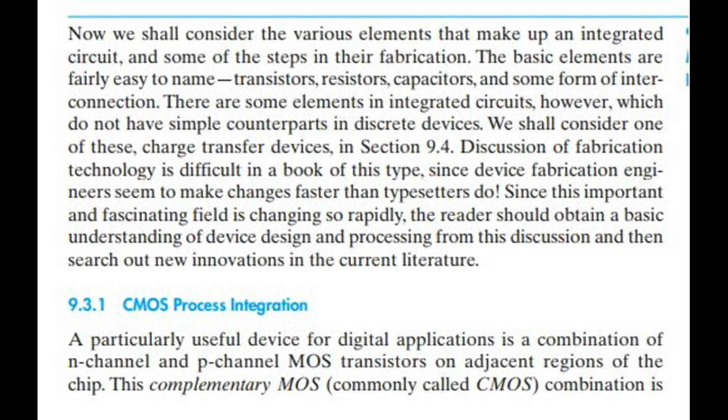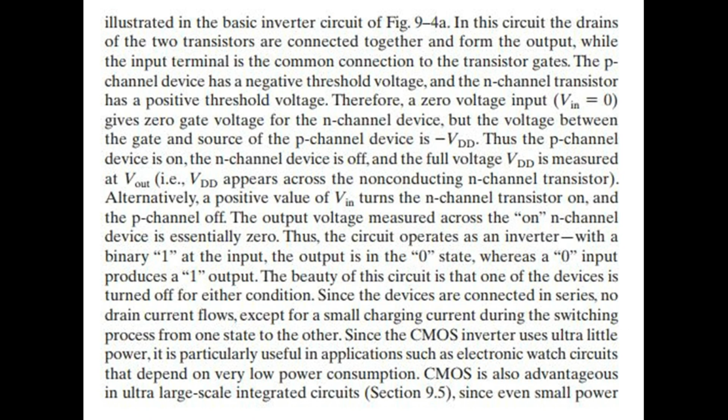Complementary metal oxide semiconductor process integration. A particularly useful device for digital applications is a combination of N-channel and P-channel metal oxide semiconductor transistors on adjacent regions of the chip. This complementary metal oxide semiconductor, commonly called CMOS, combination is illustrated in the basic inverter circuit of Fig 9.4a.